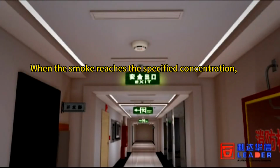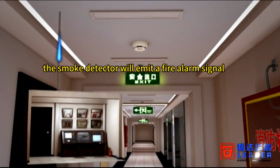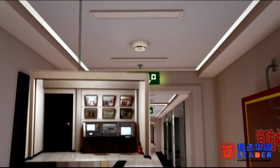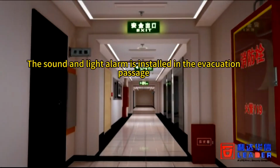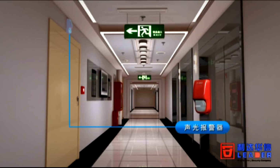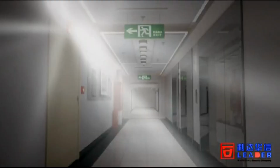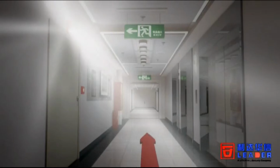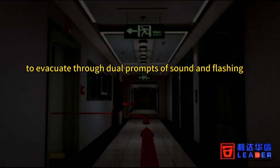When the smoke reaches the specified concentration, the smoke detector will emit a fire alarm signal and transmit it to the fire alarm controller in the central control room. The sound and light alarm is installed in the evacuation passage and at the entrance of the evacuation passage. In noisy or low visibility environments, sound and light alarms can guide people to evacuate through dual prompts of sound and flashing.